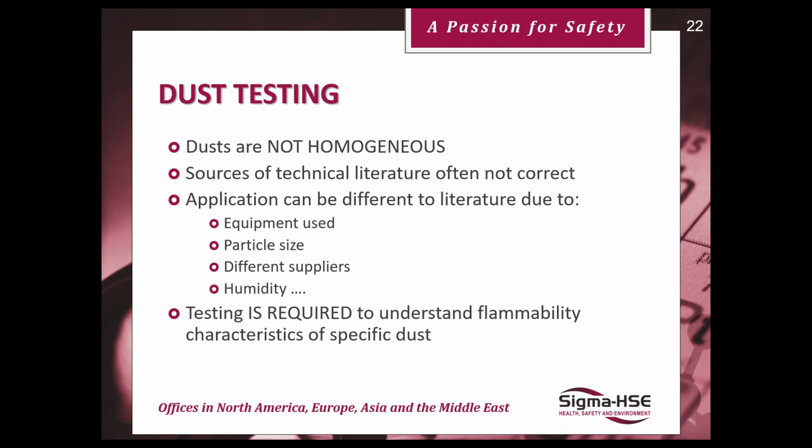For example, there are very many different types of flour, all of which will have totally different minimum explosible concentrations, minimum ignition temperatures, and so on. Primarily because of particle size distribution, but also other factors as well. We can only get at this by testing.